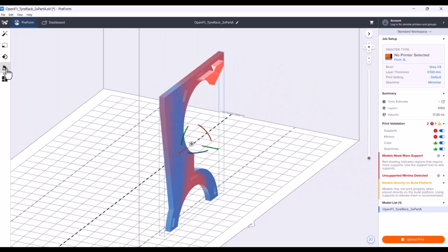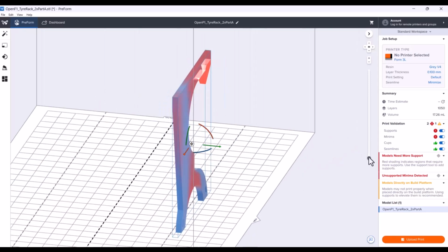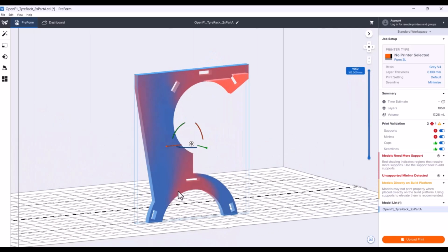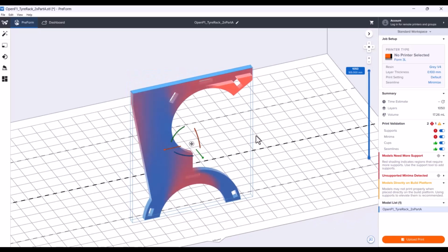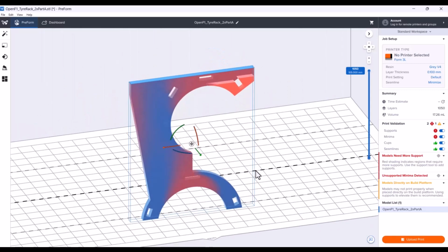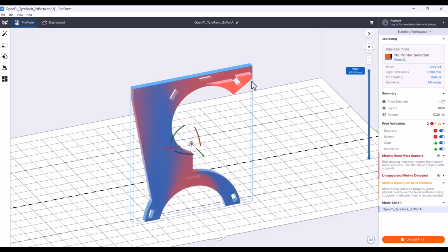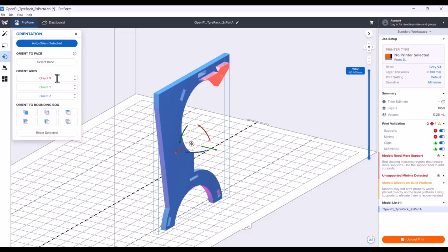So what we're probably going to want to do is go the route of the whole 30-degree thing. Technically you actually could print this standing straight up because you can see the cross-section is really thin moving up, and we don't really have any serious features in here. You do have some cradling with the tires that fit in there and in here. So you potentially could get away with it. But you're going to have some supports printed up in here, so it'd probably be better just to orient it. What I might do is 60 degrees.